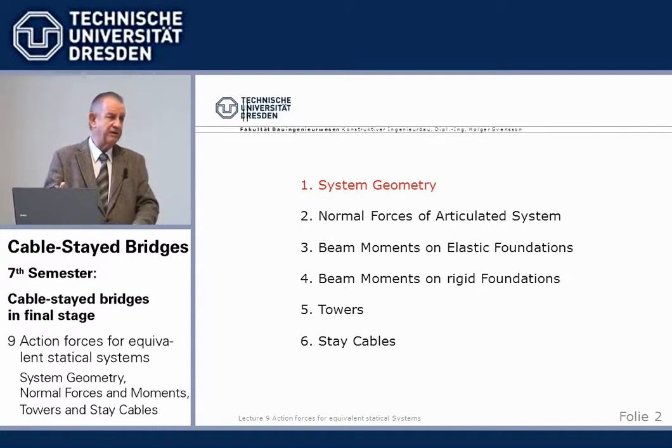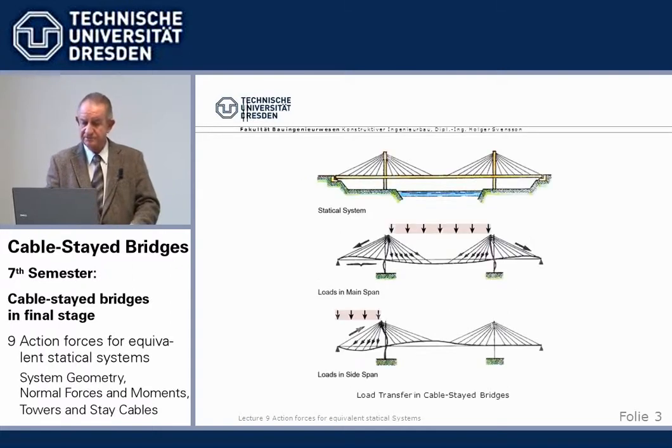And for all these cases, we will touch on non-linear theory, which in German we used to call second-order theory. In English, it's sometimes also called P-delta. So those 3 are used in the same meaning. Nonlinear theory, second-order theory, or P-delta effects are equivalent.